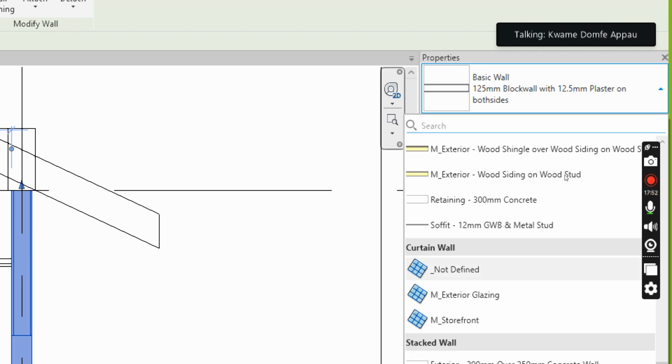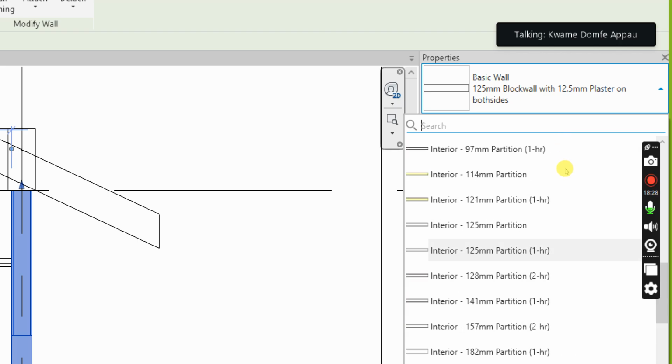So these curtain walls, for instance, if you want to use them in your design, might not reflect the type of curtain wall that you want, which means that you have to be able to take one of the curtain walls and then edit the curtain wall, edit the mullions, edit the infills, edit the boundaries, edit anything so that it can behave the way you want it to behave. If you don't edit an object, that object cannot behave or assume the structure that you want.